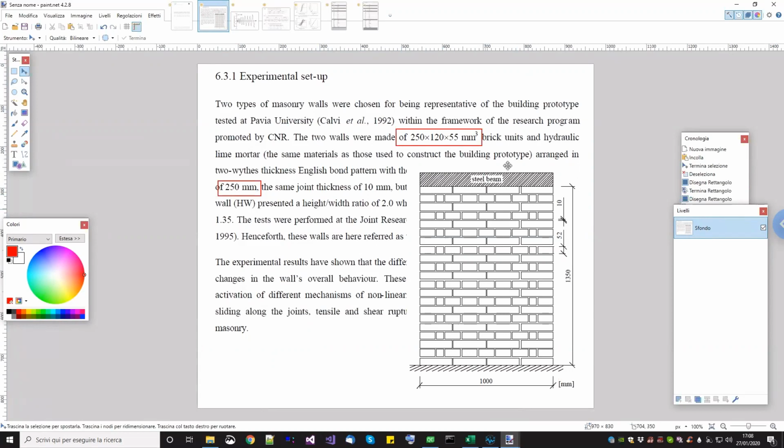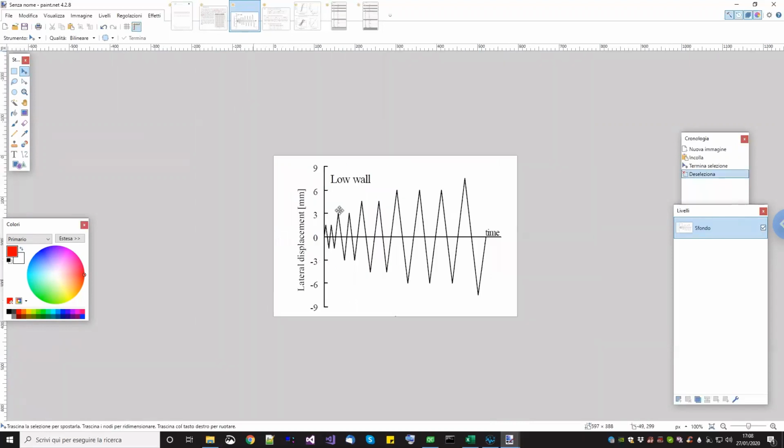Then we are going to apply first a vertical displacement. Then I will show you how to apply a fixed rotation at the top beam when you are dealing only with 2 degrees of freedom displacements, UX and UY. And then in the second stage of the analysis, we are going to apply an imposed cyclic displacement on the top beam.